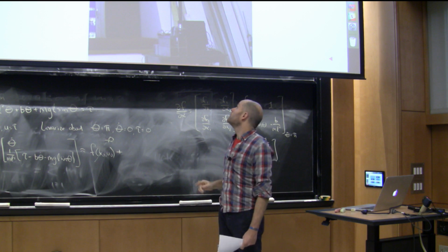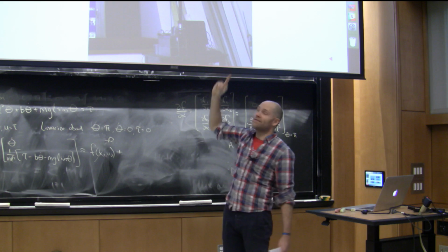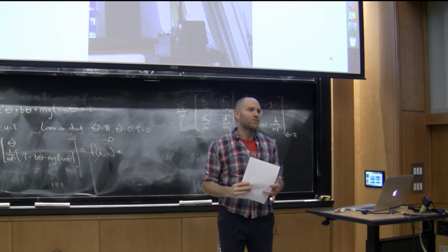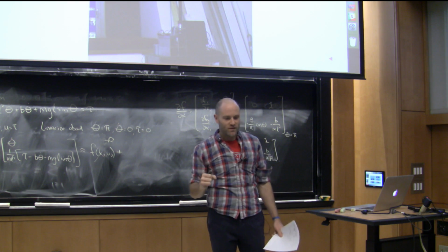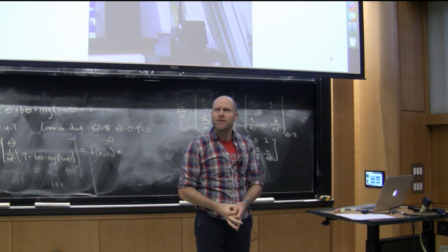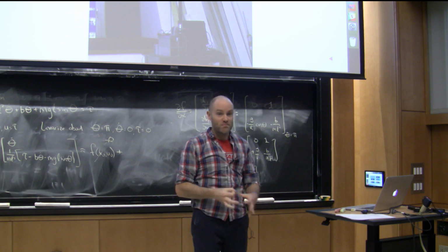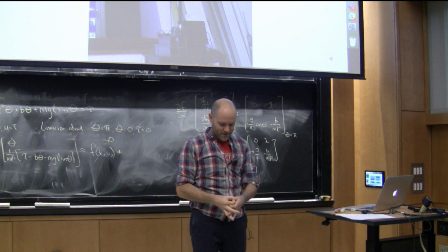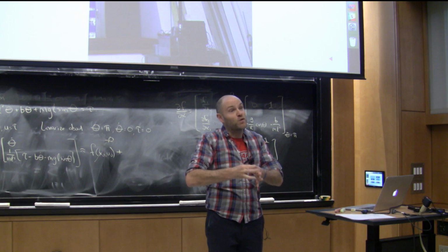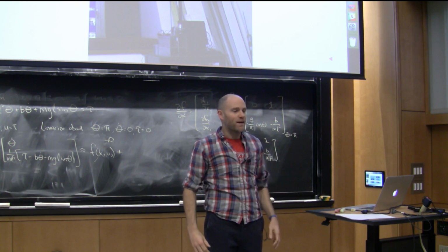Okay. So okay, but now you put your engineering hats on here. Why is it jostling at the top? Good. I think that is the biggest reason. So we actually designed a slip drive. Is that what it's called? I just blanked on the name, but it's an unconventional transmission, which is meant to have almost no backlash. But even that amount of backlash still gets us. So it's got a drive, but it's actually got a rubber interface between the torquing shaft and the output shaft, which is designed to have no backlash. But even trying to minimize it, it's still got some backlash.